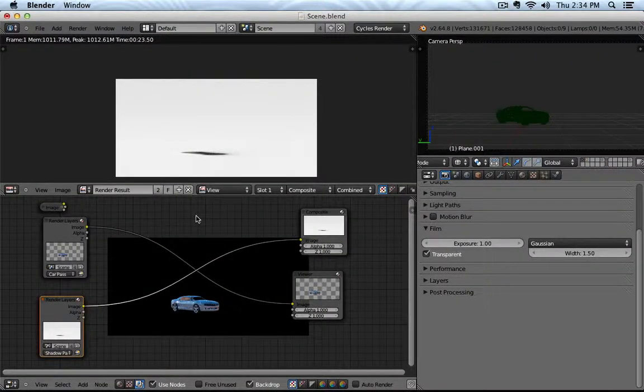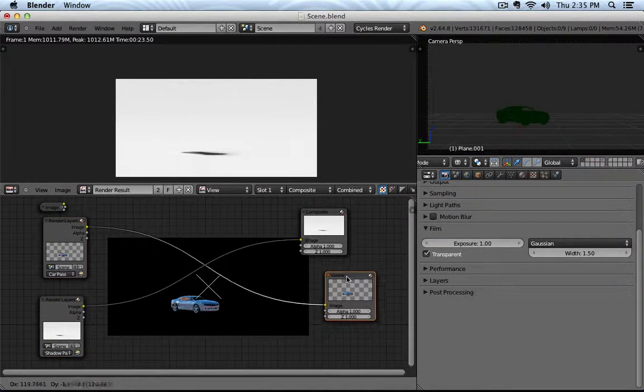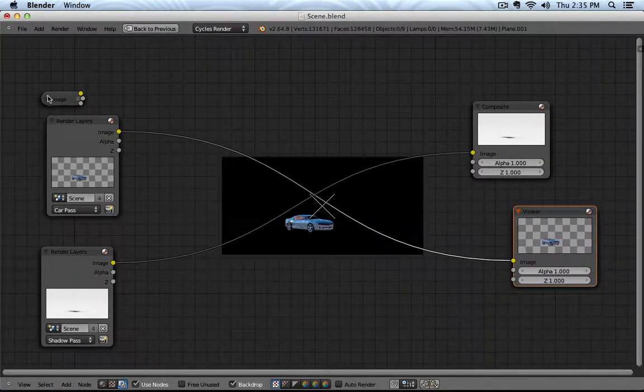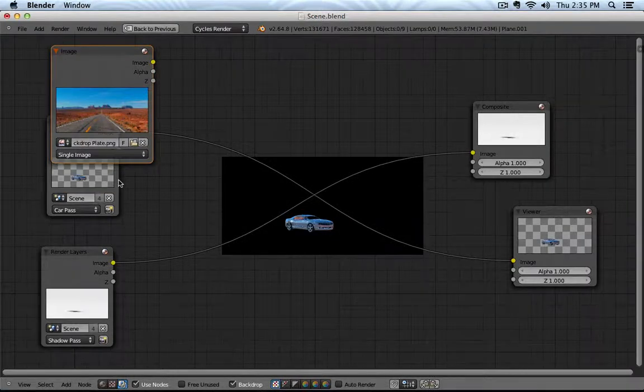Because what can happen, maybe at the beginning you might hit F12 by accident, and then if you hit F12 you update each render layer, and you don't want to do this, which is why each time I clicked only on the camera for those layers, so those render layers selectively will only be updated.